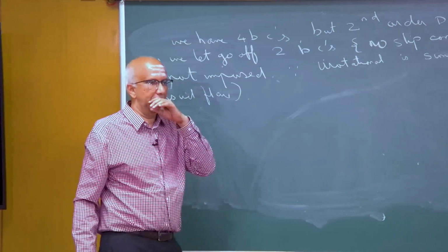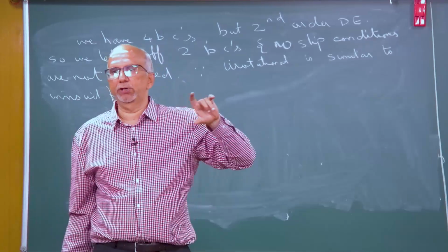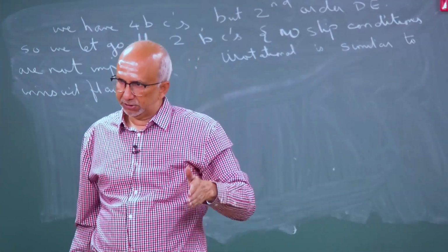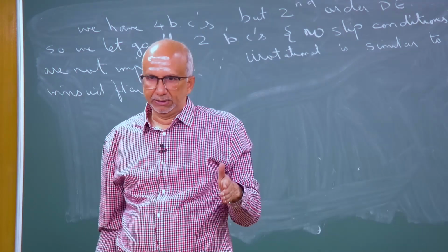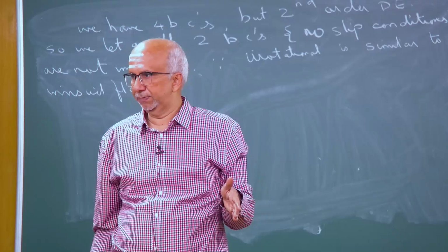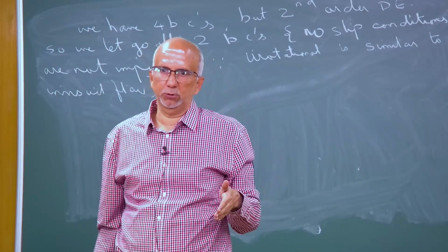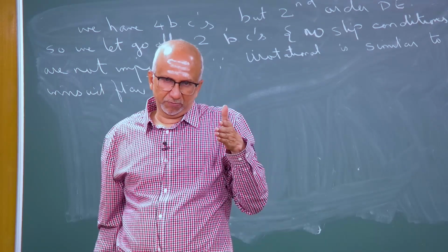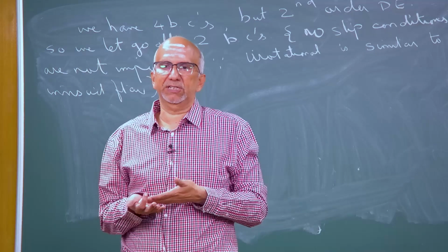So, for example, in reaction engineering you have the plug flow reactor. In the plug flow reactor we say that the velocity profile is uniform across the cross section. There the no slip condition is not satisfied. That is an example of an irrotational flow. When the velocity is uniform across the cross section, when do you have uniform velocity? When there are no viscous effects.